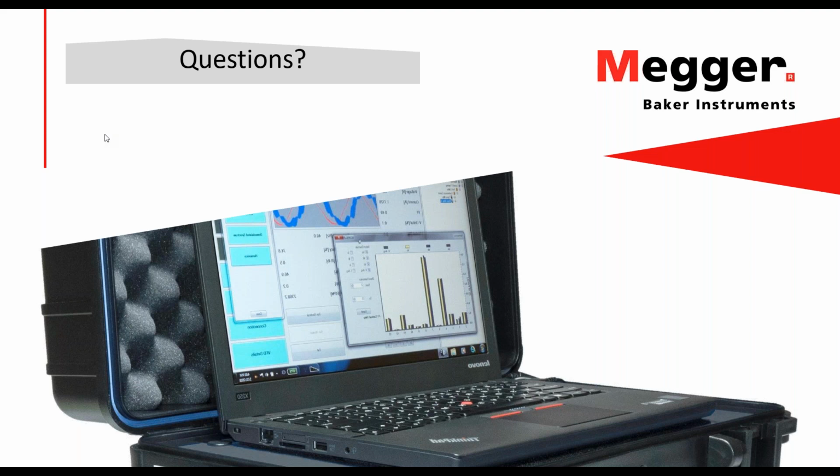Back over to Leslie. Are actual motor parameters such as stator resistance and reactance essential for accurate dynamic analysis? So it is important. Nameplate information is important to us. So knowing the voltage of the motor, the horsepower, the amps of that motor are all very important properties to know.